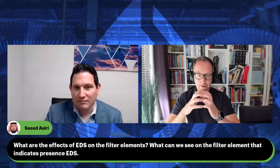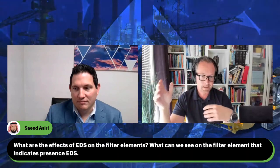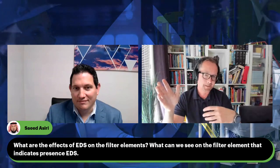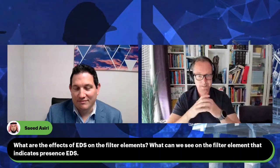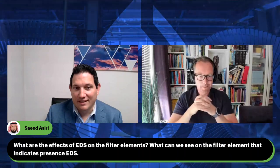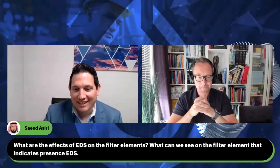But the scary part is that we have also seen filter elements that have been running for a very long time with ESDs, and at some point the filters are so damaged that the crackling stops, because they are so damaged that the hydraulic load is going down, and letting everything through instead. So it just bypasses, right? Yeah.